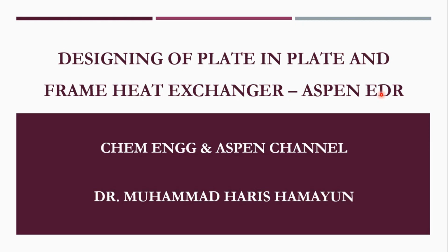The important point in this tutorial is that we are not treating the heat exchanger as a black box. We will look at the design from the perspective of the individual heat transfer plate and then see how these plates come together to form the complete exchanger. We will also examine important design parameters such as chevron angle, plate thickness, plate pitch, pore diameter, heat transfer area, pressure drop, and many more. This makes the tutorial particularly useful for anyone interested in heat exchanger design, process equipment design, and Aspen EDR.